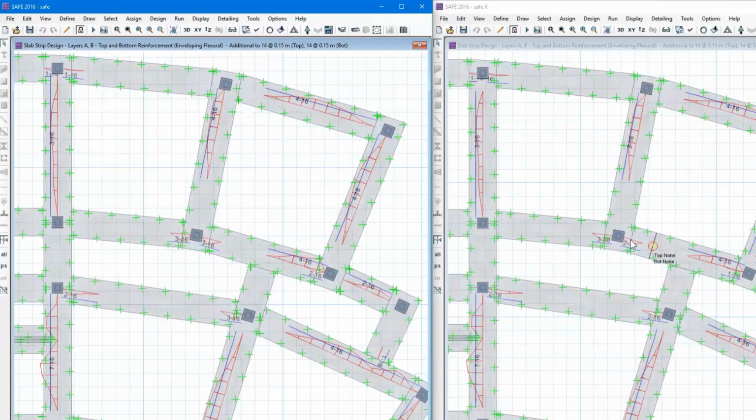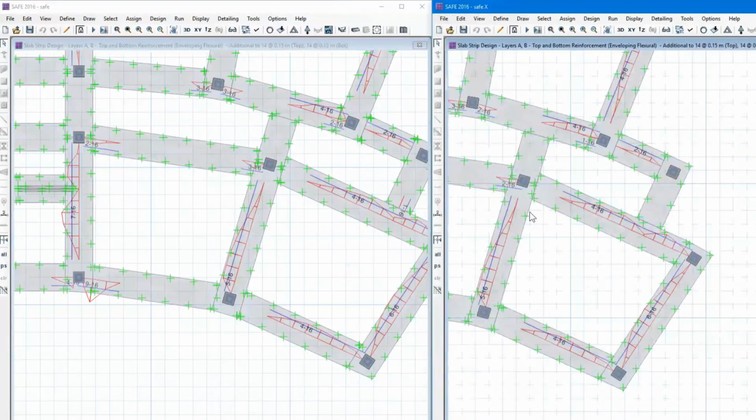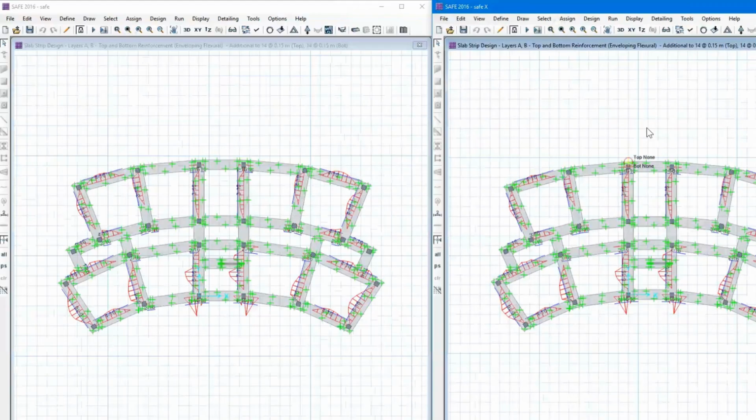Even the reinforcement development lengths are different, because the theoretical and practical cutoff points change. This means incorrect local axis orientation does not only affect bar quantity, it also changes reinforcement length, anchorage zones, and detailing requirements. In some projects, the difference may be small, but in complex foundations, the error can become very significant.